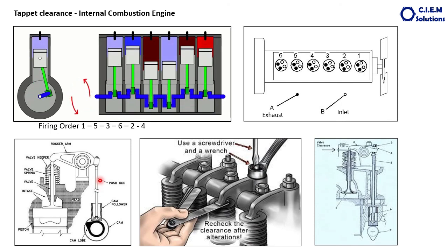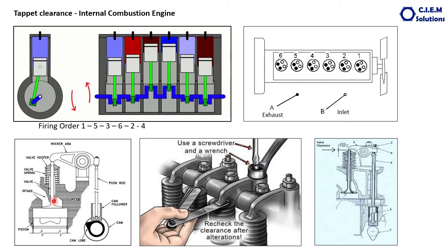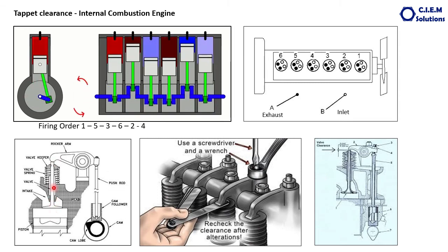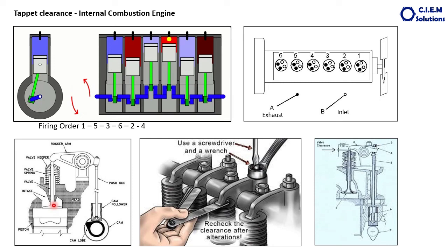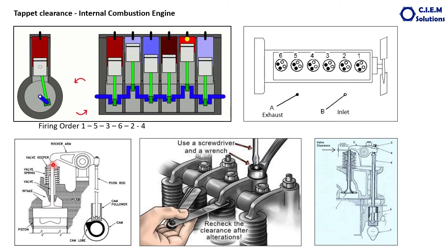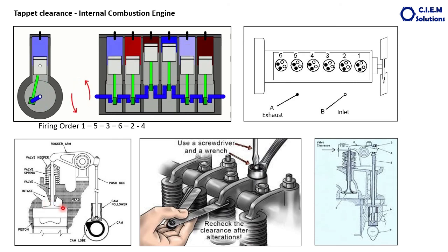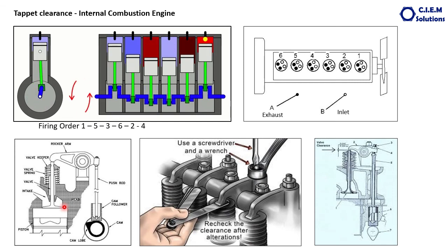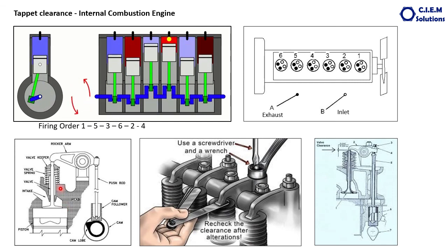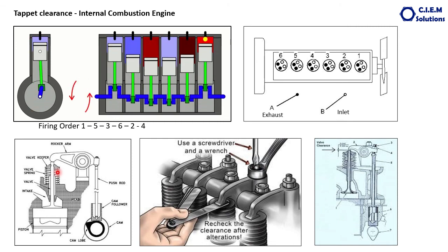What happens if the gap is less, that is, the valve lash is less? Early opening of the valve: the valve will open a little bit early. Point number 2, incomplete closure of the valve because of the less gap here, and also mixing of the fresh air with the exhaust gases. Second, there is a loss of power and a possibility of excess fuel consumption, and there will be unwanted load on these springs, which may cause further failure of the springs, etc.